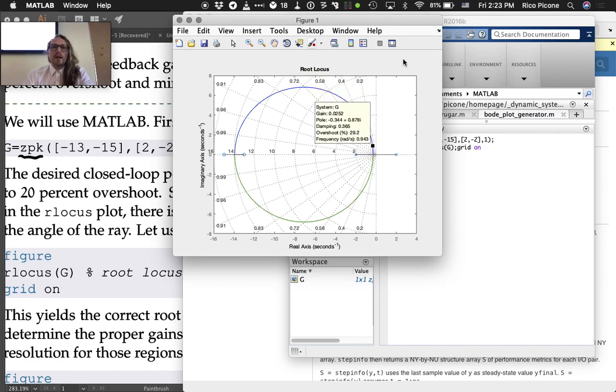We want a 20% overshoot, which you go from 0 here to 29.2% overshoot at that point. So we've got a big jump there. But there's going to be a crossover point at which we had 20% overshoot. But if you keep going, we're going to increase past 20% overshoot, and then we're going to come back to it. Okay, it's 22.4% overshoot there, 19% overshoot here. So between these 2 points somewhere is the 20% overshoot line that we're aiming for, right?